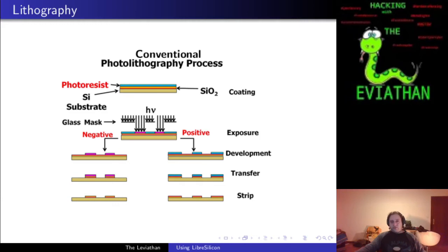In its principle, it's the same as developing a photograph. You have a photoactive resist, which is deposited onto a wafer using spin coating. After that, you use UV light, which you focus and beam through a mask of some sort on which your pattern is painted.